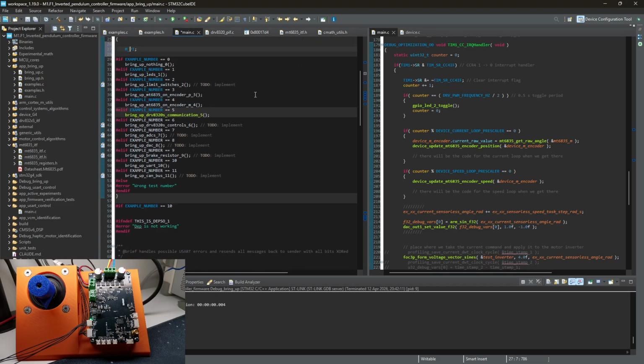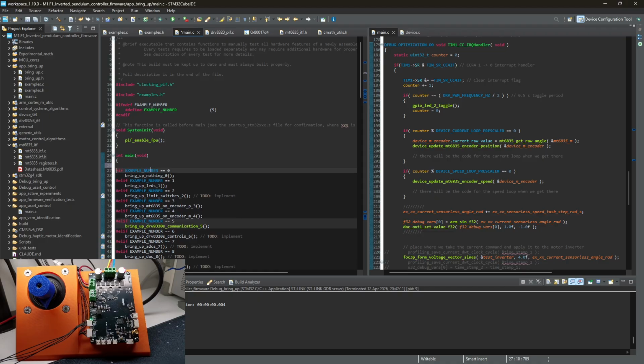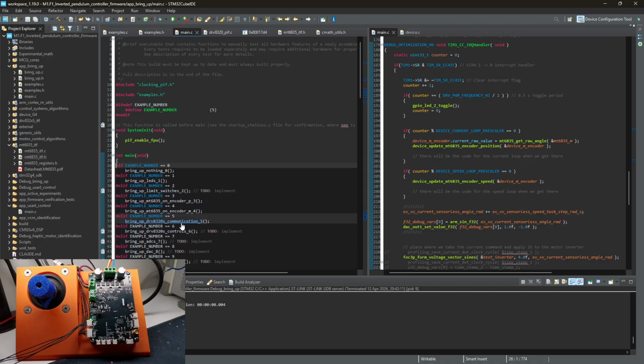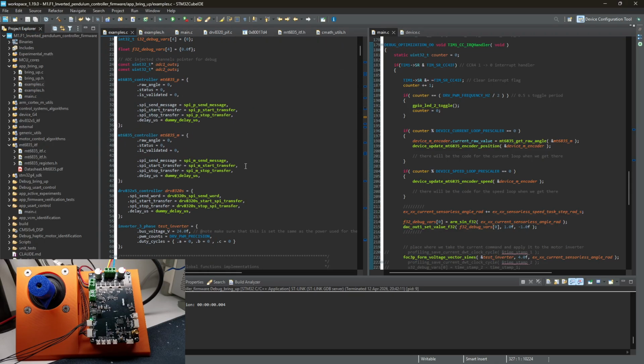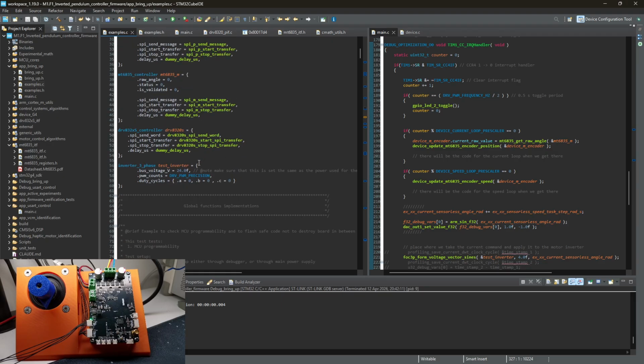But also, yes, actually, there are some problems. For example, when you define a lot of variables, when you have a big project, similar to what I have now, roughly, and you open up, for example, this example file, and we open up the definitions we need, and we need a lot of stuff. We need encoders, motors, everything has a struct, and you define the default values. And if somewhere here you have a float, and you define it like this, you already add a double to float conversion to your code, and first of all, your flash becomes huge because conversion from float to double takes quite a lot of operations. Then you can force the math to be double math, and it can mess up things a lot. But there is a way.